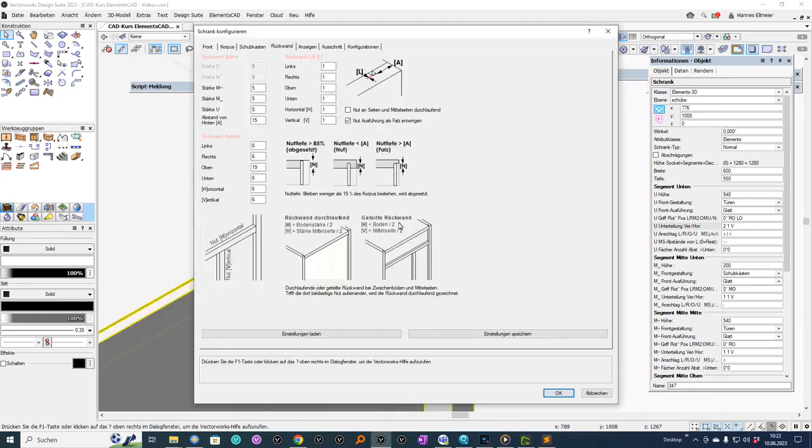It is always relevant to refer back to what is stated in the help section, and in the footer of the help, it states that no dado cuts will be generated if groove on sides and middle sides is continuous is set. Otherwise, subtraction bodies are always drawn. For CNC output, it is sometimes relevant to simply generate continuous grooves.